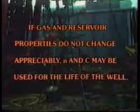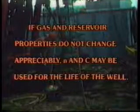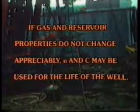It can be shown that N and C, which the conventional test assumes to be constants, are in reality functions of such properties as viscosity, temperature, gas compressibility factor, reservoir permeability, net pay thickness, wellbore damage, wellbore radius, and drainage radius. If these factors do not change appreciably, the same deliverability data may be used for the life of the well. In practice, though, the gas properties will change, and so will N and C.